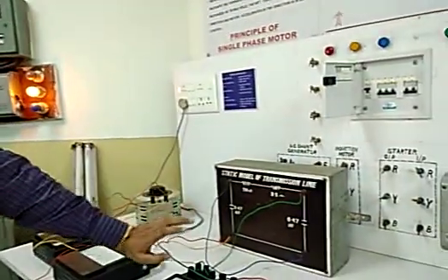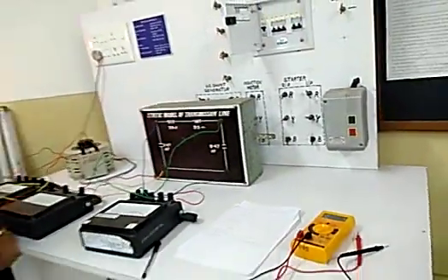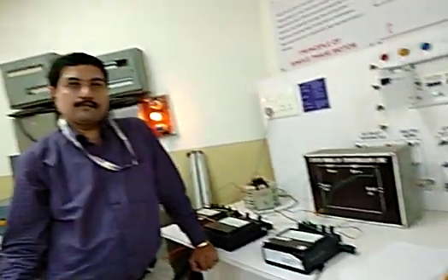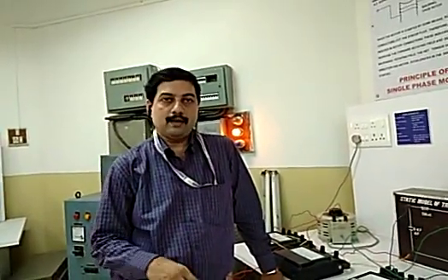And by using the corresponding line parameters R, L, C and the length of the line, you have to calculate the corresponding values of the ABCD constants. And then you have to compare the ABCD constants calculated practically and the ABCD constants calculated theoretically, whether they are the same or not.